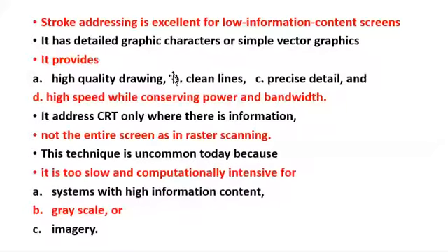This stroke scanning addressing is very excellent whenever you have a CRT that needs low information content. And of course, it has another advantage: it gives detailed graphic characters and simple vector graphics, that is, the information that will be formed on the screen. It is of the same high quality, despite the fact that it doesn't require much work as compared to the raster, where we have to scan twice.